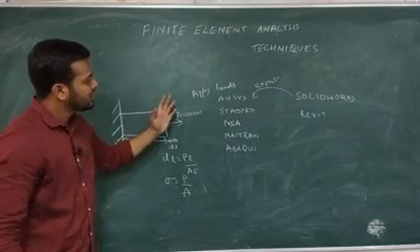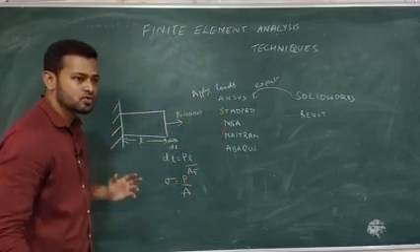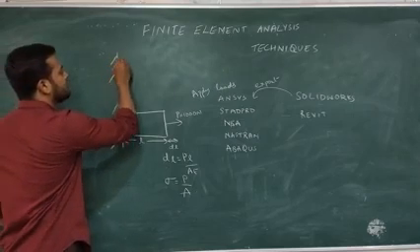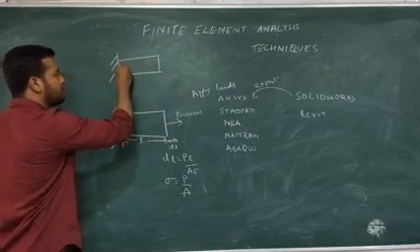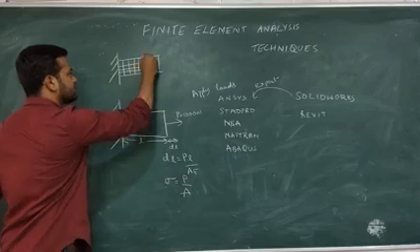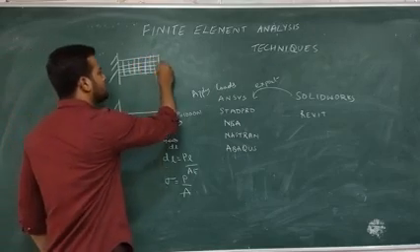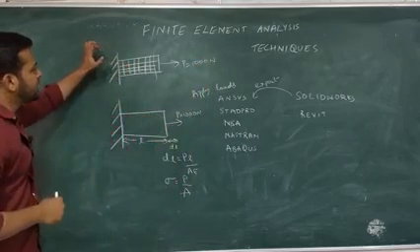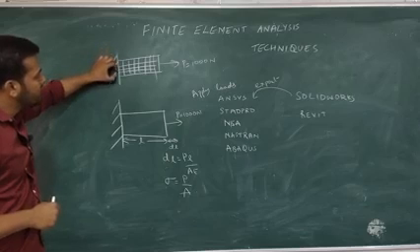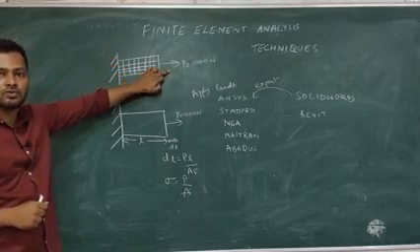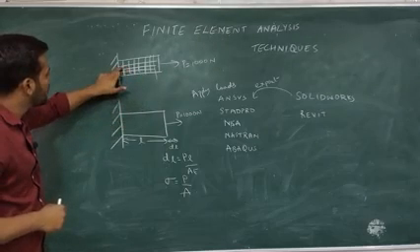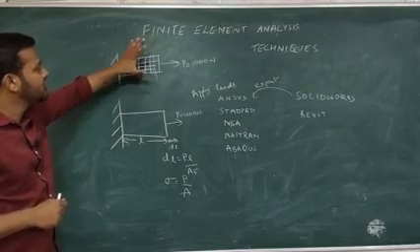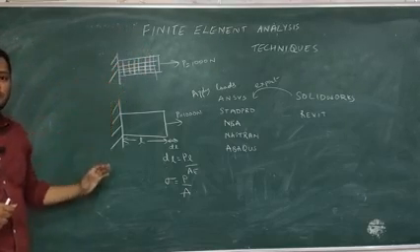The main idea of this technique is to divide a model into a number of small and simpler elements. So what a finite element software does, what a design software does, is it will divide this model into a number of elements. Okay. So after applying load, let's say I am applying a load of P equals 1000 newtons, we can analyze the behavior of each and every element because of this load. Behavior in the sense, how much this element will elongate, and what are the stresses developed in each and every element of this model can be analyzed by using finite element techniques.